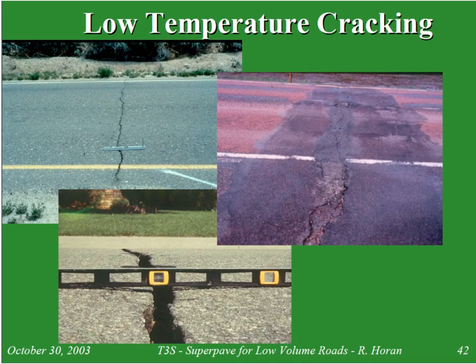Another thing to think about is low temperature cracking. Again, this is part of the SuperPave program. One of the conclusions that came out of the SuperPave program is that when you have low temperatures within your asphalt, the asphalt will start to shrink.